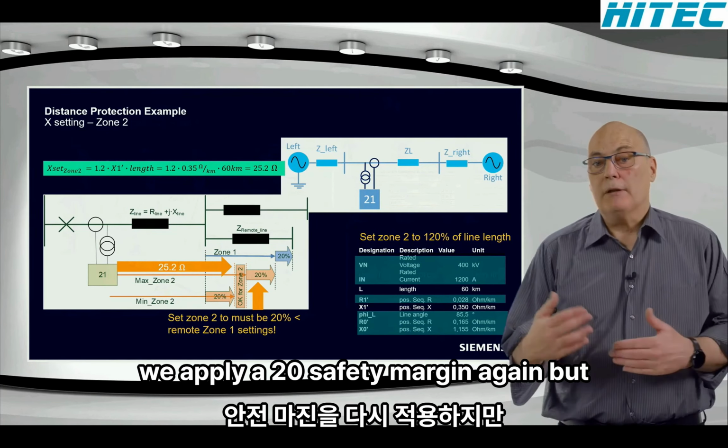All right, just to conclude, we are going to apply the fault resistance settings based on arc resistance over here and the X setting based on the tolerances over there. But before we conclude, we must remember that the R fault we are using here for the setting is going to be different in the RMD, and only for the phase to ground loops. The RMD technique is the alternative to the classic distance protection. The RMD protection uses a different way to calculate the ground fault resistance, only that one setting, and that one you then apply directly.